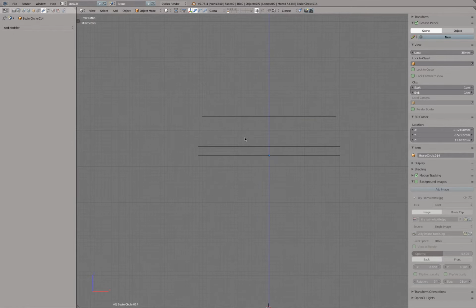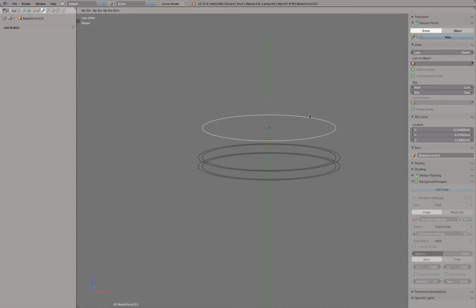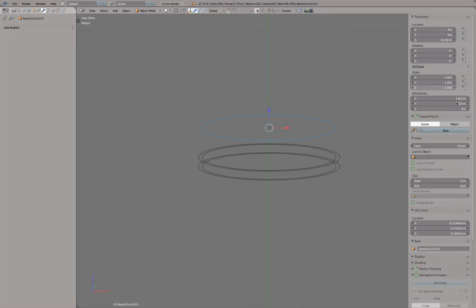Now, the next step is actually, there is a small dip in here. So let's select this ring, Shift D, and then let me quickly measure that distance. So for example, I think this one is roughly, as it seems, yeah, 30 millimeters. Okay, press enter, go to transform, and then we say here 30 millimeters and 30 millimeters.